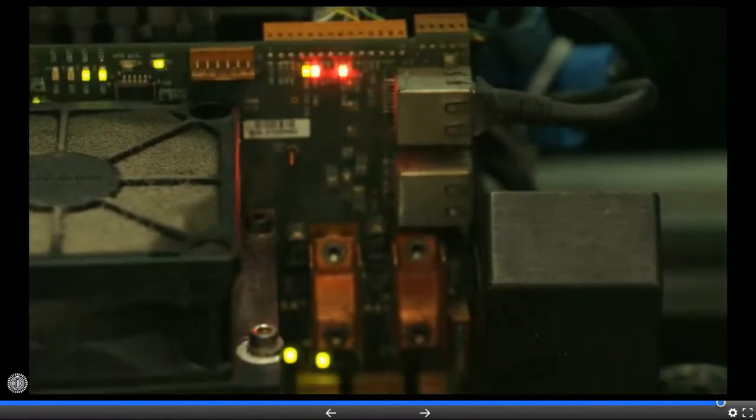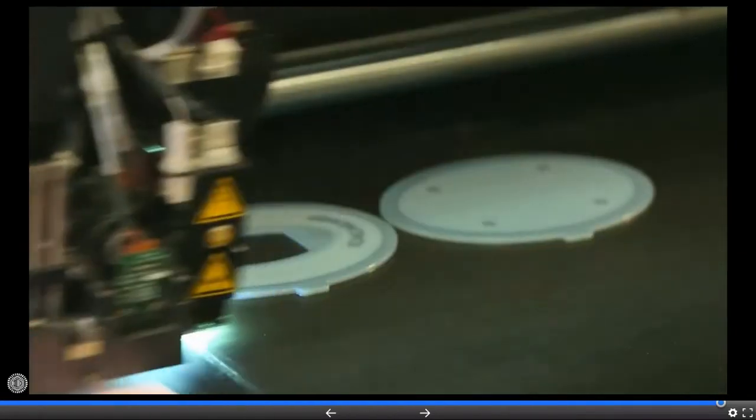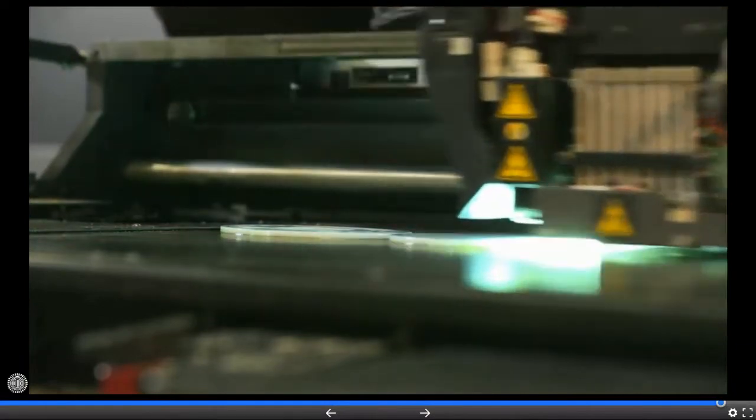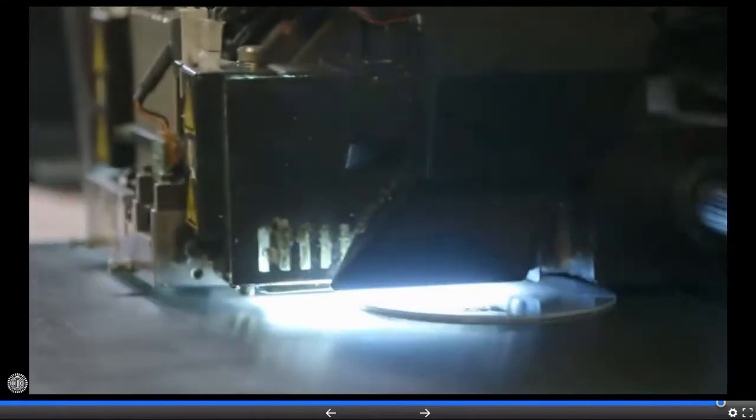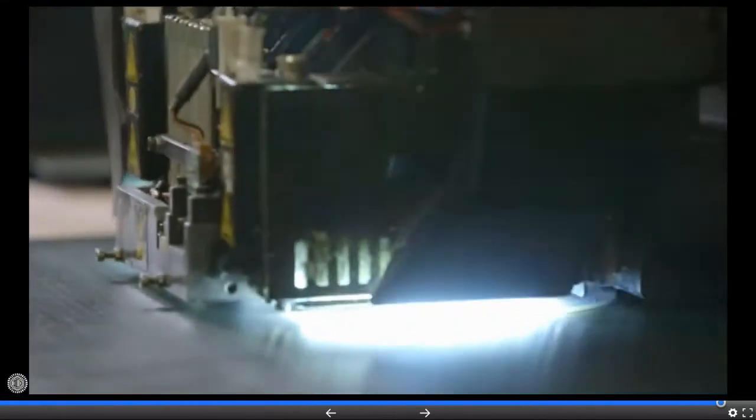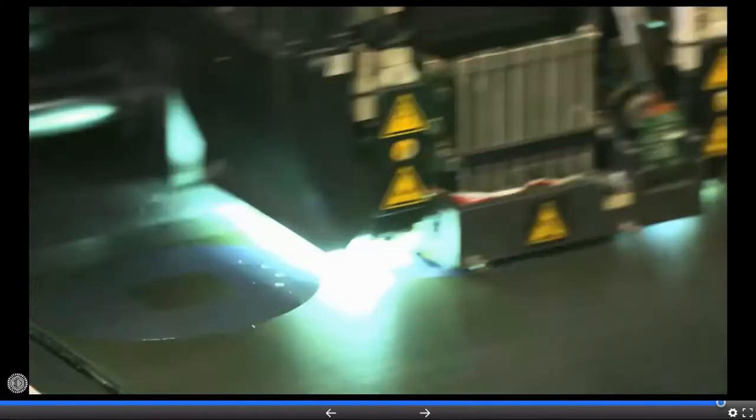The PolyJet process extrudes out or jets out a liquid resin that can be cured with a UV light. They are made to react to ultraviolet light. And so that's the catalyst that causes these two separate components to come together to form the third, solid plastic component. So with the PolyJet system, it jets out a thin layer of the photopolymer resin. It cures it with the UV light and then builds a cross section of that part layer by layer.